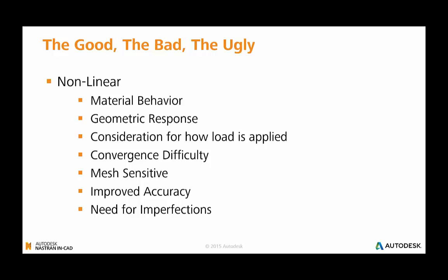So if we look at the nonlinear analysis, obviously now we're considering nonlinear material and geometric response. So we're considering the change in the shape and stiffness of our part. We also need to consider how we're applying the loads as well. There can be issues obtaining convergence, hence the need to start with a linear analysis.